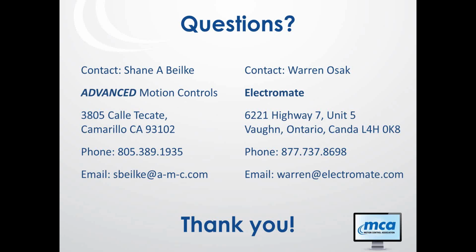We have another question from the audience. What is the maximum efficiency achieved by a servo drive for these kinds of applications? On axes with manipulators at lower power, dealing with a permanent magnet brushless motor, you're going to be upwards of 98%. And on your larger axes where you're doing traction, you're going to be at 95%.